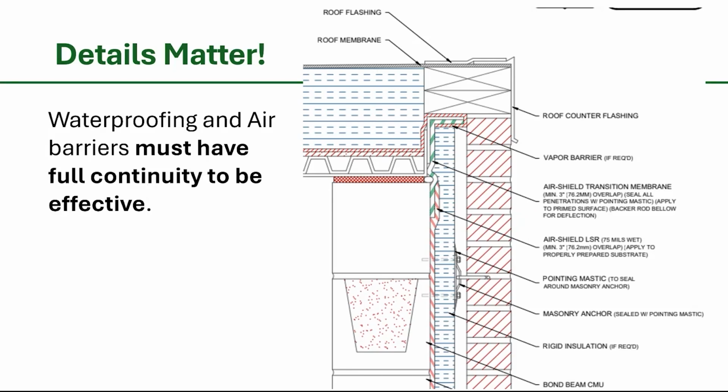So at some point, you need to be able to run a red pen around the entire building in any given section and have it not lift off of the continuous air barrier or air control layer. There's a number of ways to do it. You can use the roofing membrane as your air control layer, and that would mean that you'd have to bring that down and connect the air barrier up to it on that blocking underneath coping flashing there. You can also bring it onto the top of the roof deck underneath the insulation.